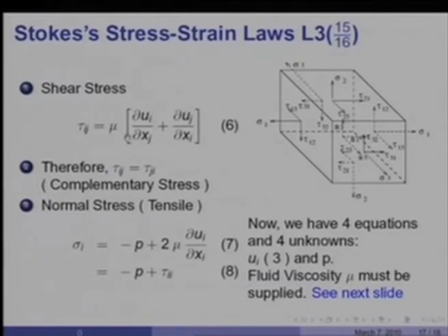But there are fluids like blood or polymers and so on and so forth, in which the magnitude of viscosity itself depends on the rate of strain, and sometimes on the manner in which the fluid was strained through time, and therefore, viscosity also happens to be a function of time, a function of the flow in which the fluid is situated, and so on and so forth.